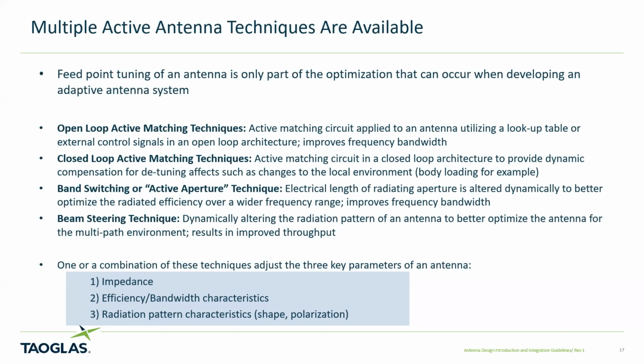That is a passive antenna, so conceptually it's an easy step to say, let's take the passive antenna with the passive matching circuit, pull out one of the fixed capacitors and drop in a tunable capacitor. It really worked out well, because if you go back to 2005, 2006 through 2010, 2011, look at the companies that were developing tunable capacitors: Cavendish Kinetics, Peregrine, RFMD. A lot of companies developed a tunable capacitor that could provide dynamic variation of capacitance, and you drop it into a matching circuit. Now you've got a tunable antenna. But you need control signals to determine when to tune the antenna, and what I am tuning to. I'll briefly touch on that.